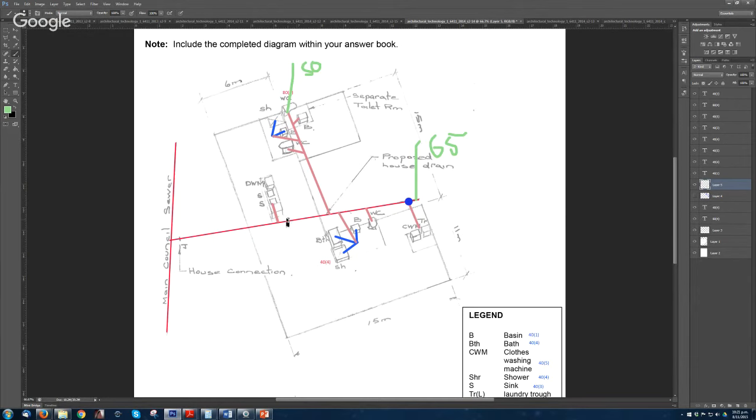And I think Joseph's asking, floor waste gully is when two or more pipes come together, like shower, bath, basin. Yeah, it's just so you don't have many pipes going to that, because if you had 3, you'd have 1, 2, 3. On this one, you just have 1 that's going there. I think it just makes it easier for the plumber to make all those connections. So I put a vent here, and I think I'll add a vent here as well.